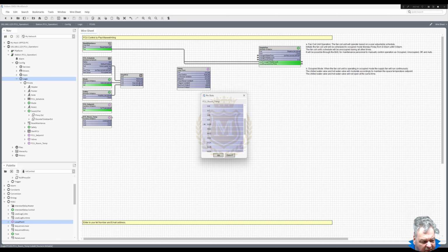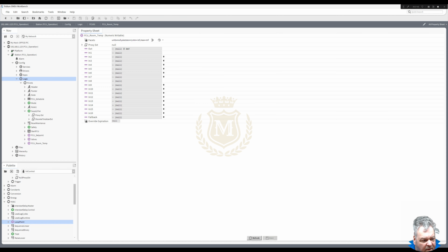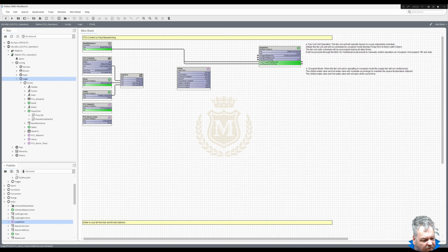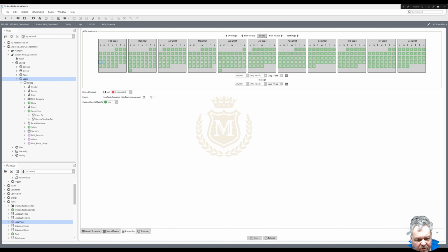And we'll take out in 16, that's going to be Fahrenheit. We don't need our min and our max, so minus inf, plus inf. Okay, save. And we'll put something in there at the moment of, I don't know, 70 degrees, so it's colder than that. Put our set point into there. With our loop enable true at the moment, but we will move that once our scheduler is in. In fact, let's put our scheduler on for Sunday.